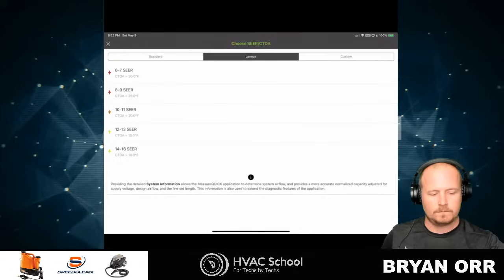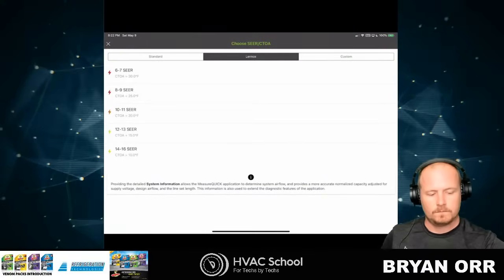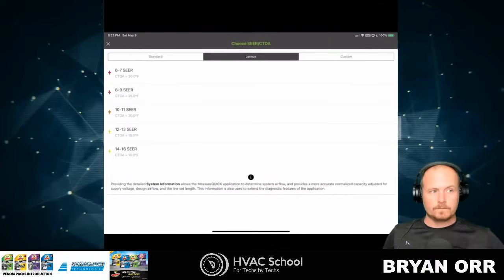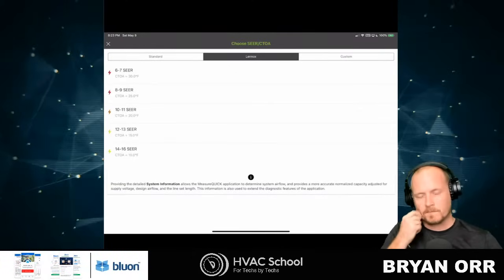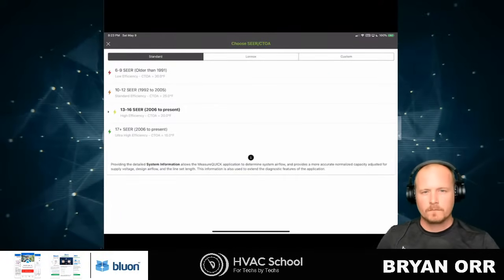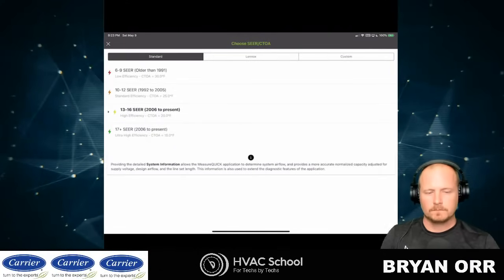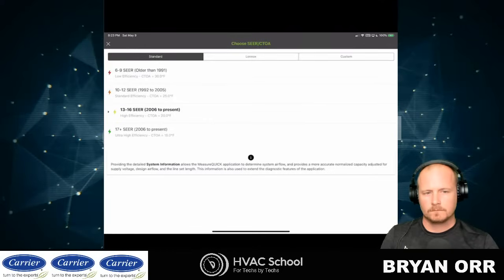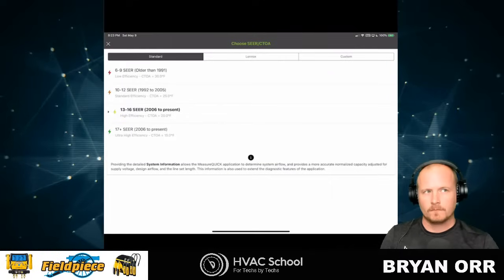And right now we have to rely on you to go through and set the profile, and if it gets the profile right, it's going to get you in the ballpark for where the pressure should be. But typically when you see, like in the diagnostics, just a low suction pressure or a high suction pressure or a low head pressure or a high head pressure but no other symptoms, that typically just means that the profile is not quite right for that piece of equipment. And once you set the benchmark, it'll adjust that design temperature difference to what it actually is.